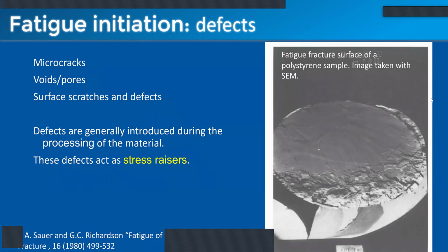So when we're doing fatigue testing, we are going to be using a materials testing device, the Instron, similar to what you used in the lab. And you're going to load and unload the material many, many times, and you're going to be testing the device to the point of failure.